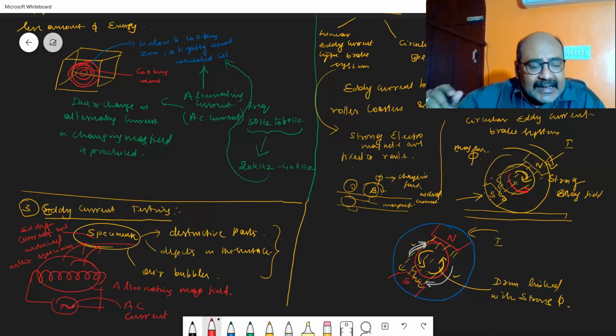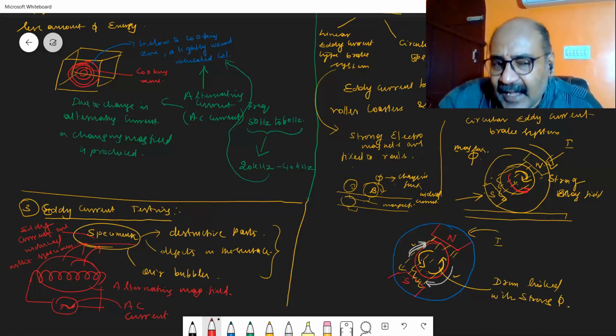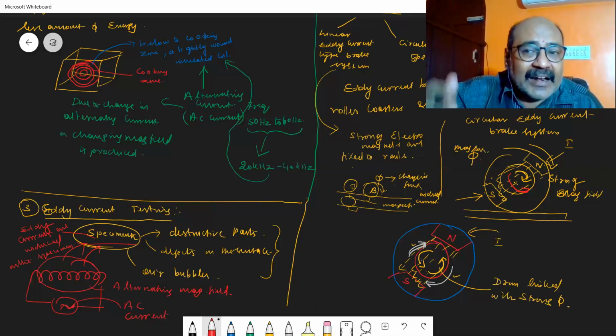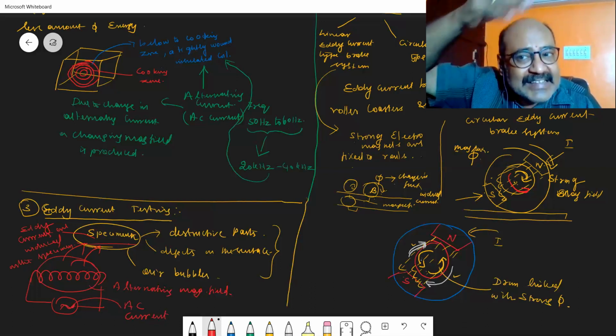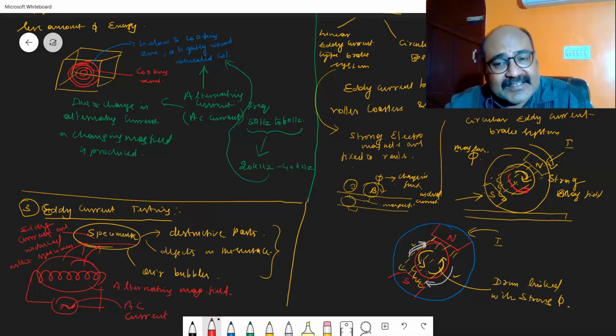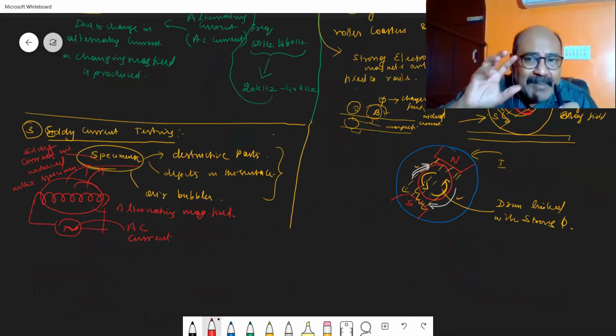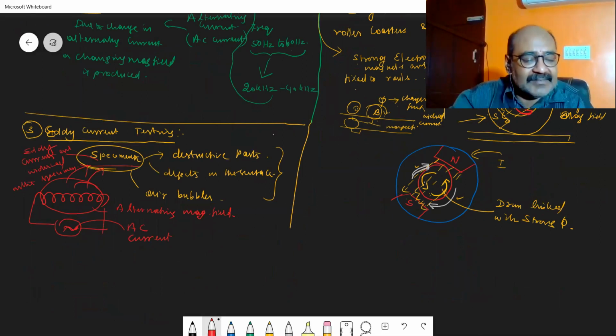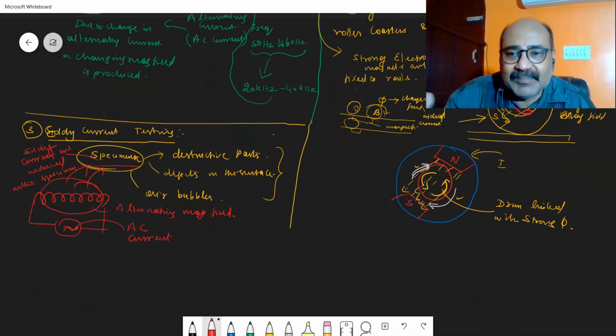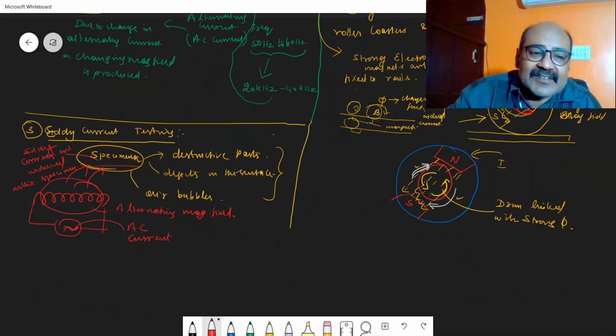The eddy currents present in that surface change if there is any defect, air bubble or crack in it. If there is a change in phase, direction or magnitude of the eddy currents, then we can say there is some defect in that testing surface. So how can you test?